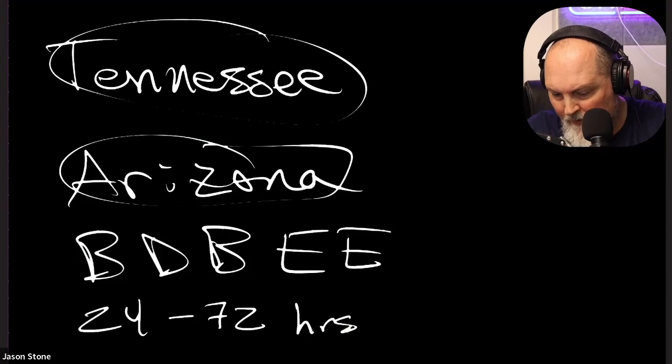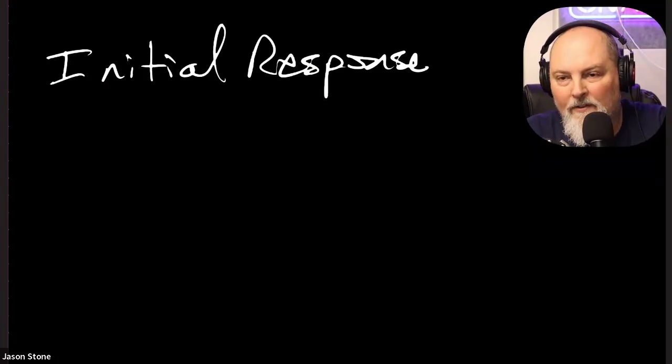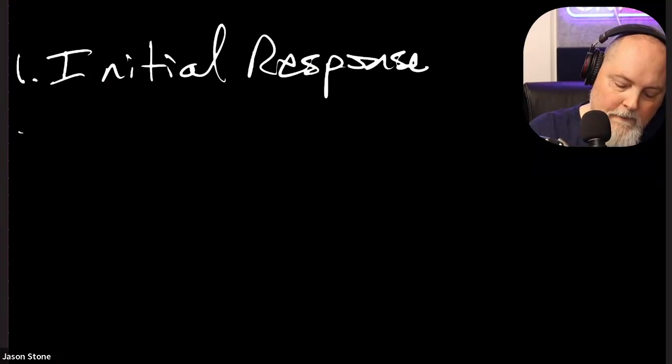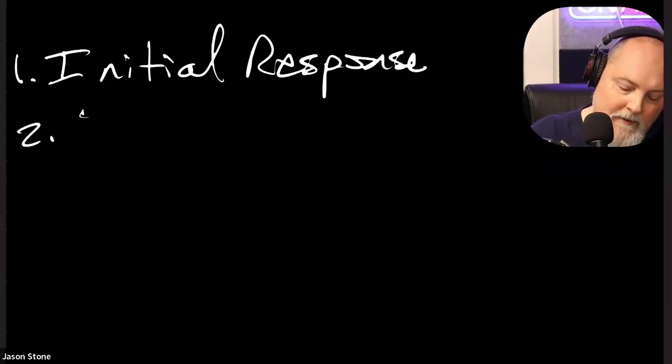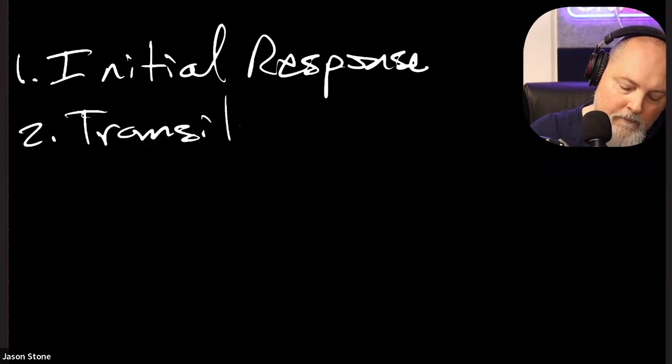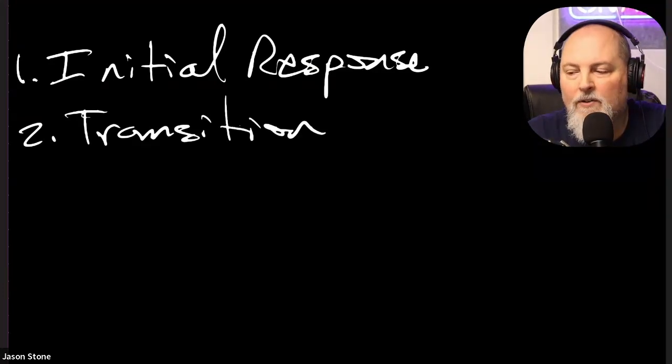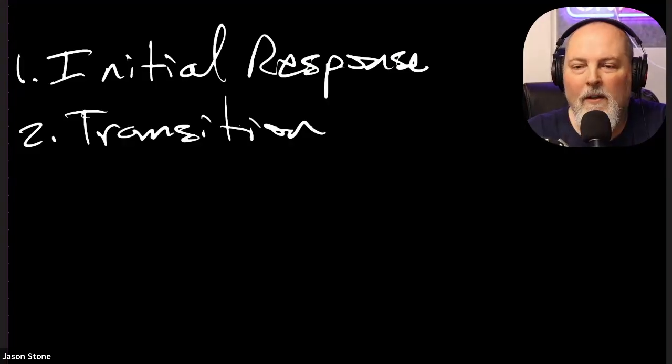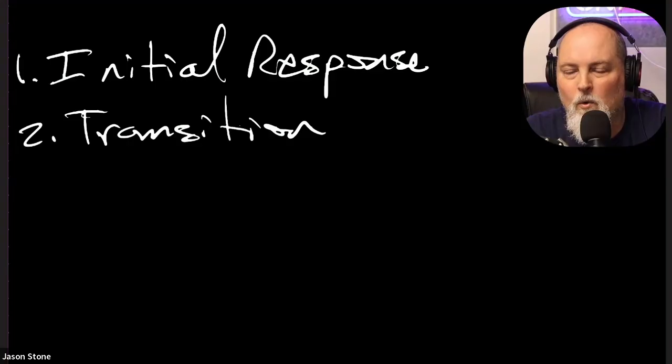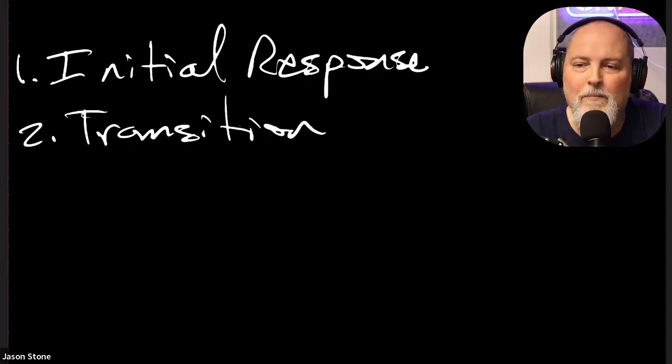This is important: there's a three-phase coping strategy. The three parts of this strategy are, number one, our initial response. The initial response uses installed safety systems. Okay, so that's phase one. Phase two of the FLEX strategy is transition. In this transition phase, we start using the on-site portable equipment. So every station has some on-site portable equipment as well, and we want to start using that.